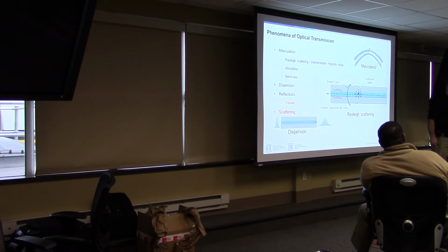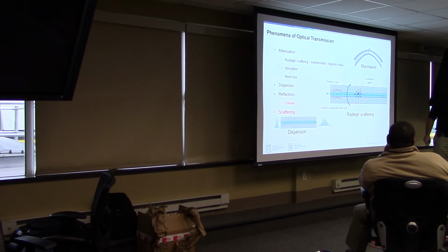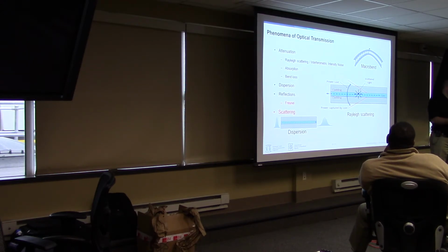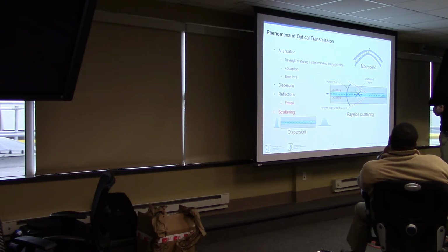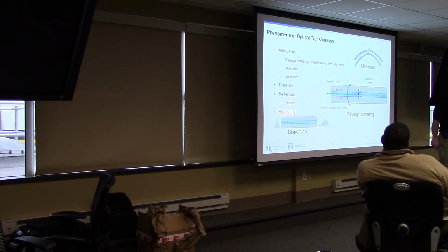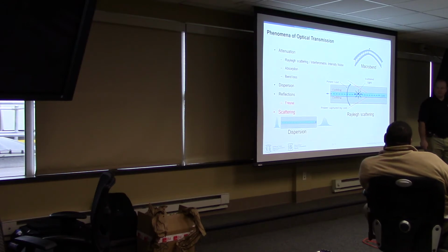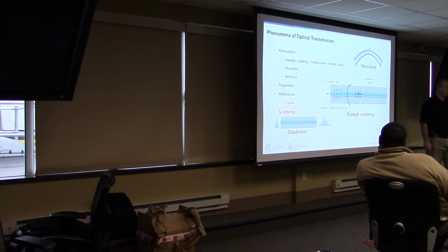Good, right? Well, what was interesting about what Jason showed, he cleaned it, and there were still problems. Sometimes you clean it, you get the dirt out of it, but there's scratches now, and you can't get those out. And those scratches could also scatter the light. So sometimes the connector is just too far gone. You can clean it all you want. Now you can see there wasn't dirt. He had cuts in the glass, and you're done. And so in that case, we're going to have to replace that connector or replace that jumper because that happens.